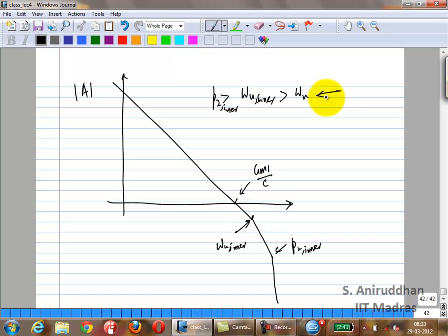So what does this tell you about the 3-stage op-amp? Fundamentally, it is going to be slower. The omega u definitely has to be smaller than what you can achieve with a 2-stage op-amp. Because of the second stage, at least in this configuration, we'll see if there are other configurations, the omega u of the 3-stage op amp is definitely going to be smaller than what you can achieve with a 2-stage op amp.